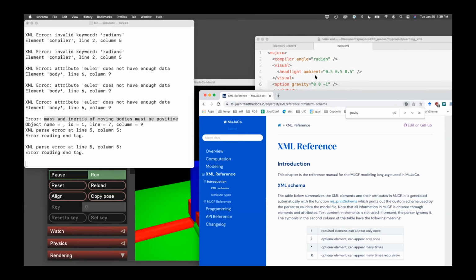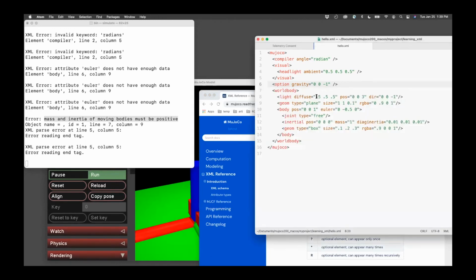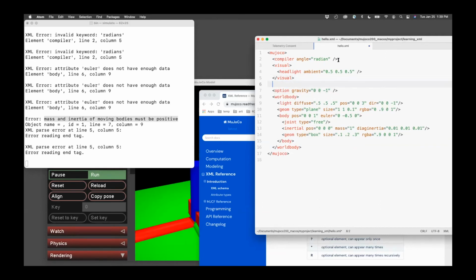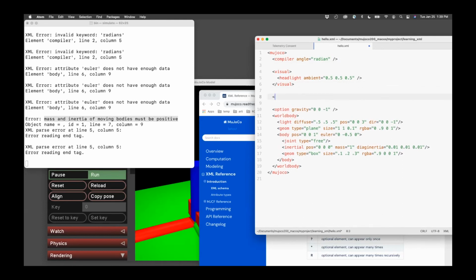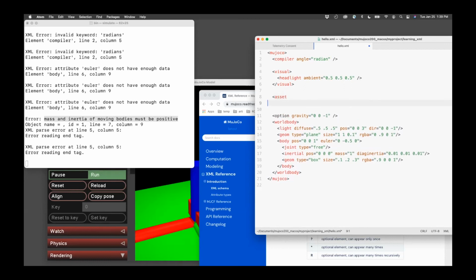That way you don't have to keep defining R. Also, you can change that value R equal to 2 and everything will be changed. So it's sort of a way of parameterizing things. There's a way in which you can parameterize things in MuJoCo. It's by using this thing called asset, and it actually works very similar to visual. So you write asset and then end it.